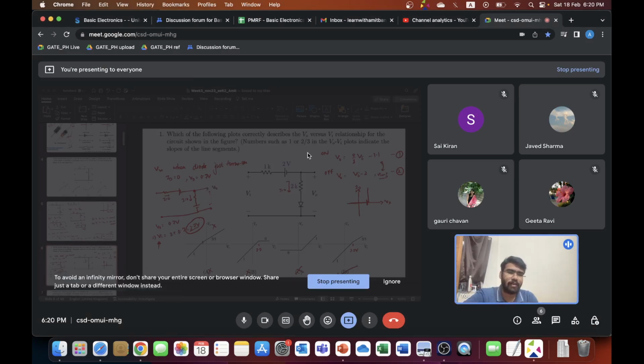So this is a diode related problem, but a diode is a non-linear device, so you must be aware of it. A resistor is a linear device, V equal to IR. But for a diode, as you saw, I versus V is an exponential relation. Still, we modeled our diode in terms of known entities, that is, a voltage source and a switch, so that we can apply all the understanding of KVL and KCL even to an exponential, non-linear device like a diode. All right, if there are no comments or doubts?